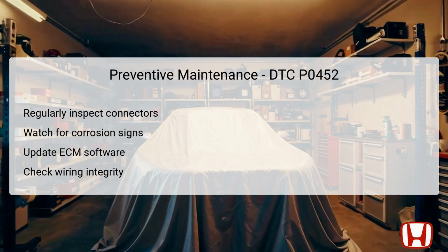Preventive maintenance plays a critical role in avoiding future issues related to DTC P0452. Regular inspections of all connectors, particularly near the fuel tank and ECM, can identify signs of wear and corrosion before they lead to faults. Corrosion can impact the connectivity and reliability of electrical signals, potentially triggering diagnostic trouble codes.